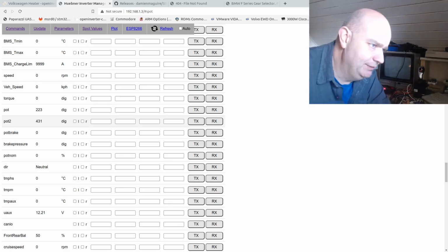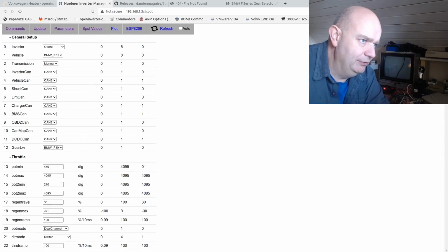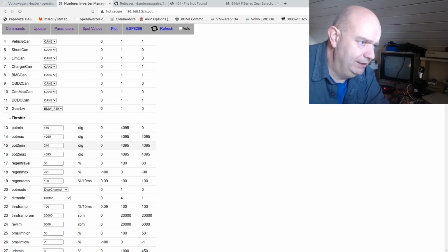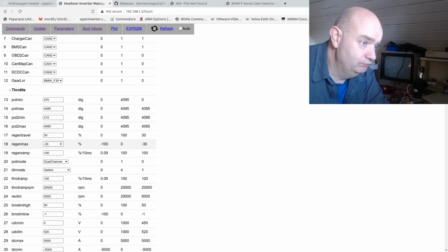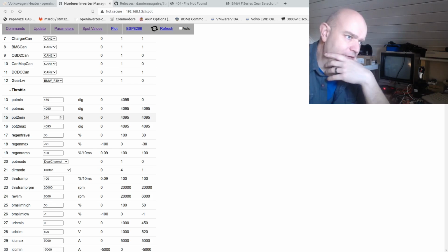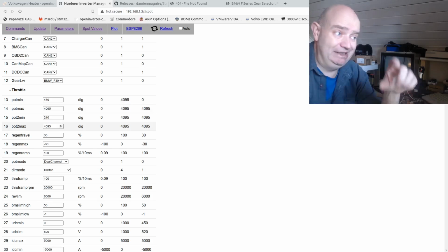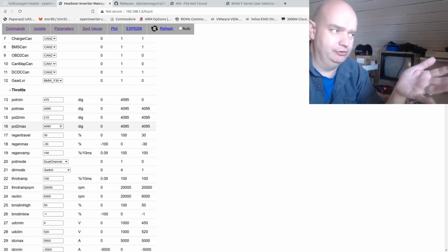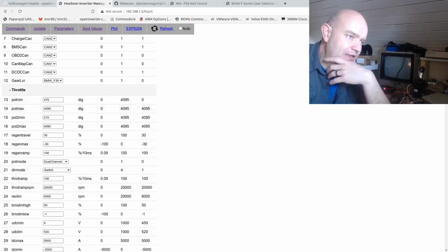It's completely released. So what we want to do then, so if we take 223 from channel 2 here, we want to make sure that our value for pot min is below that. Okay, so it's pretty straightforward. Same with the second channel, and then for the maximum value you want to make sure that this value is a little bit less so that you always get to full throttle, right? So just to clarify that,